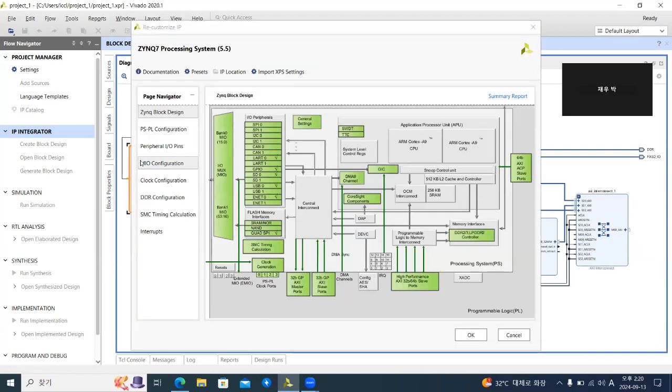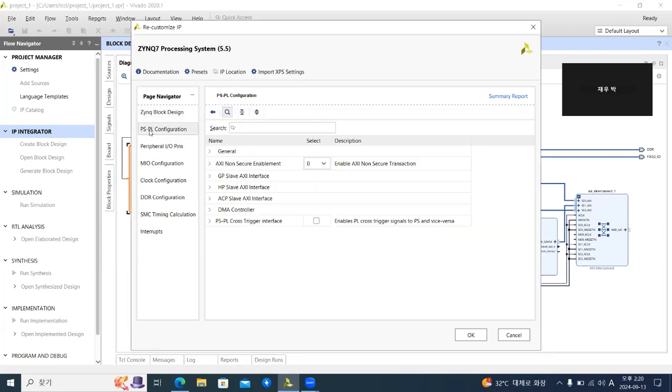This is what our CPU looks like. It's actually a small SoC. We have dual core, cache, SRAM. We actually have an interconnect inside the CPU. And whatever. We need to make use of the FPGA logic to make a new slave AXI port. You can do this by the PS-PL configuration, which is the CPU-FPGA connection.